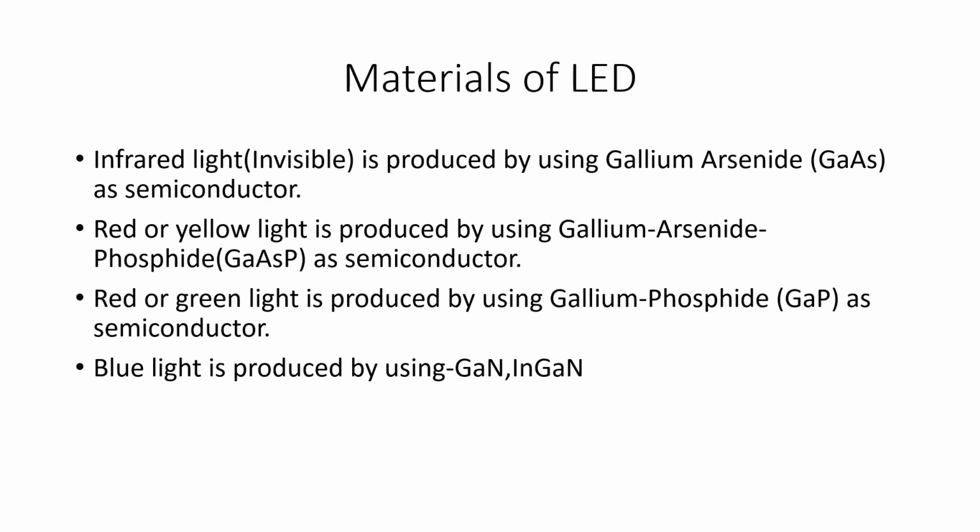So it must have an energy gap of appropriate width. The energy gap determines the wavelength of light. The material selection should be such that it must have an energy gap of appropriate width, and both N and P type must exist with low resistivity, and an efficient radiative path must be present. Like that you have to select the material to manufacture the LED.